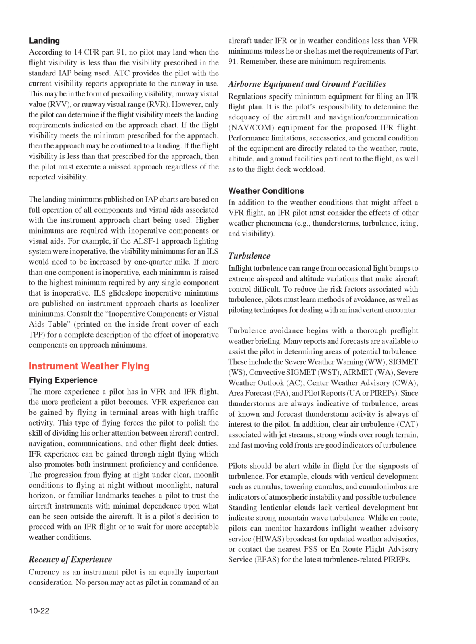Weather conditions. In addition to the weather conditions that might affect a VFR flight, an IFR pilot must consider the effects of other weather phenomena, for example, thunderstorms, turbulence, icing, and visibility. Turbulence. In-flight turbulence can range from occasional light bumps to extreme airspeed and altitude variations that make aircraft control difficult. To reduce the risk factors associated with turbulence, pilots must learn methods of avoidance, as well as piloting techniques for dealing with an inadvertent encounter.